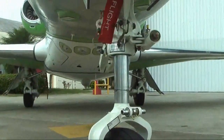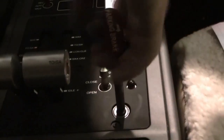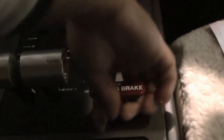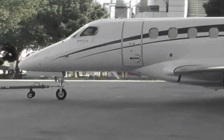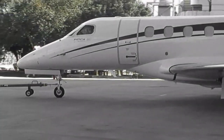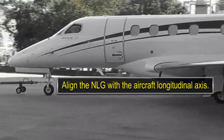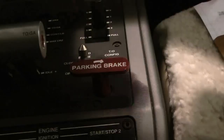Remove the wheel chocks from all tires. Release the emergency parking brake handle. Tow the airplane slowly straight ahead before turning. Complete the airplane towing in a straight line for a minimum of 3 meters, 10 feet.